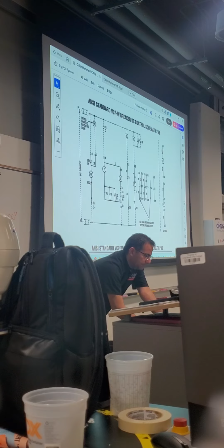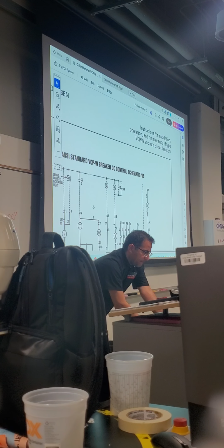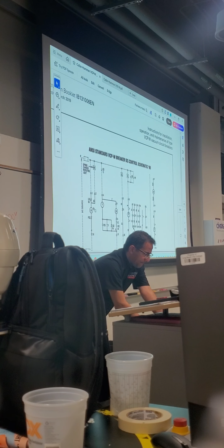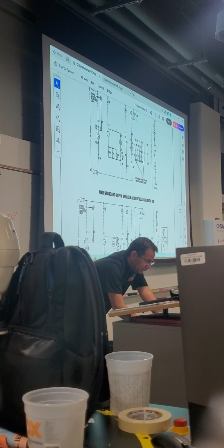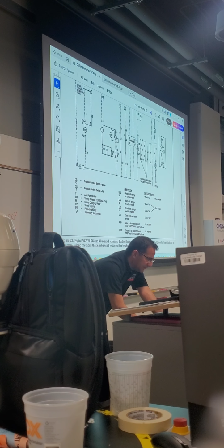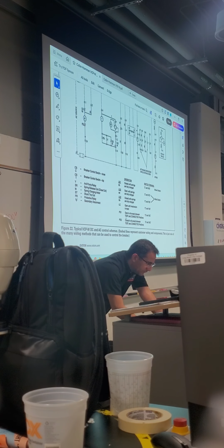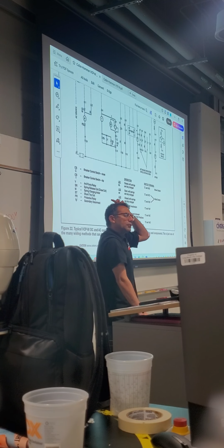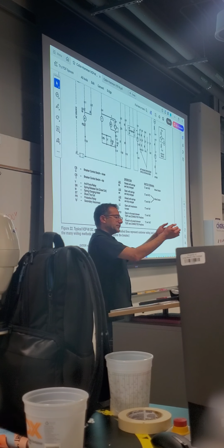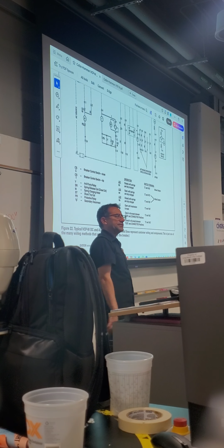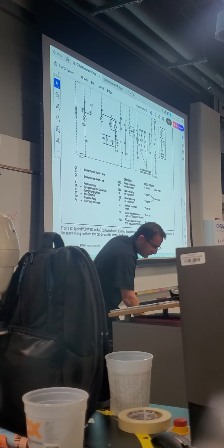Hey, just a quick question. In the top right-hand corner on the thing, it says UV. I don't see a call out for that. UV is under voltage. There's a UV in the little box. So under voltage coil. It means when the breaker is completely isolated from the circuit, that coil is gonna be energized and it's gonna trigger one of the contacts.